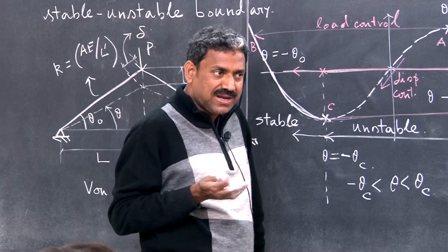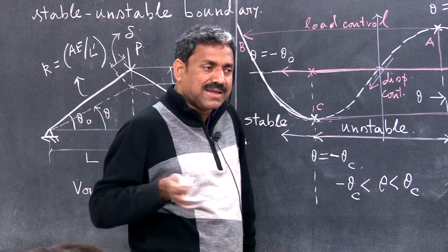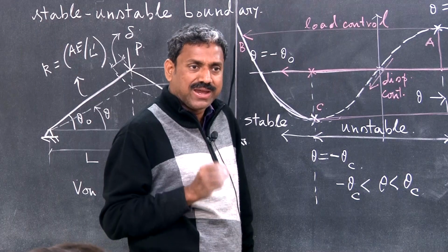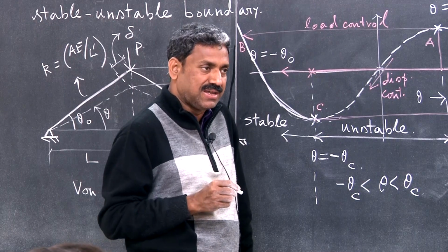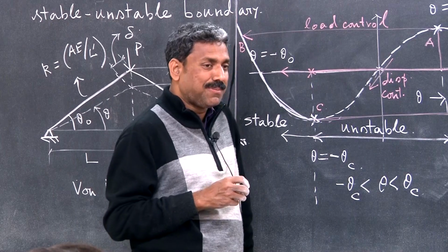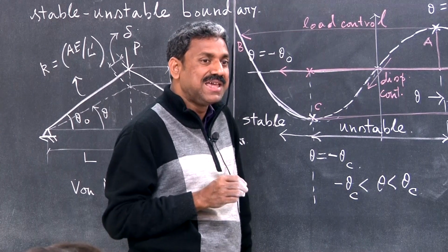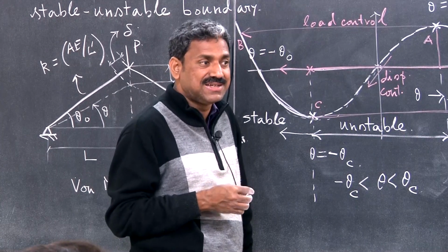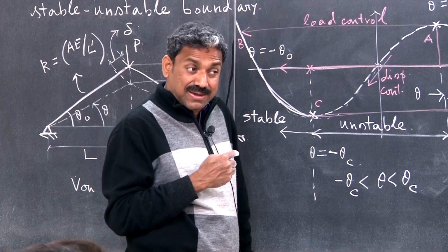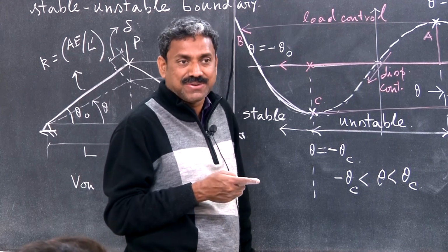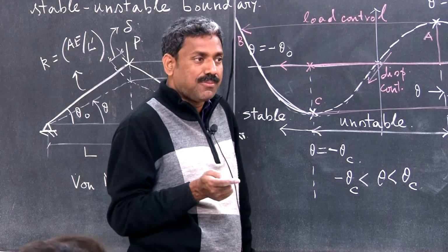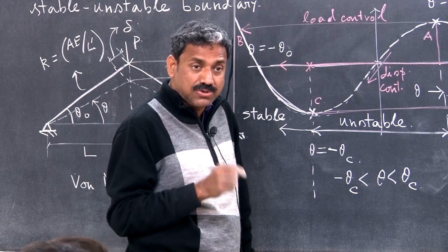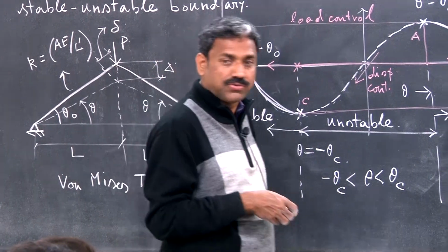By solving that eigenvalue problem, you obtain the critical load as well as the buckling mode shapes, and those mode shapes served as a legitimate basis to further simplify the potential energy function, where there will be no cross terms, or all terms will be uncoupled, right? That is what I have also demonstrated. That also helps you in tracking down the topology of the potential energy function, and by looking at just those coefficients, you can comment on the stability, right? But here, if we arbitrarily go on linearizing, it will be very misleading. That is what I am going to show now. A system which displays snap-through, you cannot linearize arbitrarily. You cannot just express this in terms of polynomial functions, and analyze based on this kind of simplification; it will be very, very misleading.